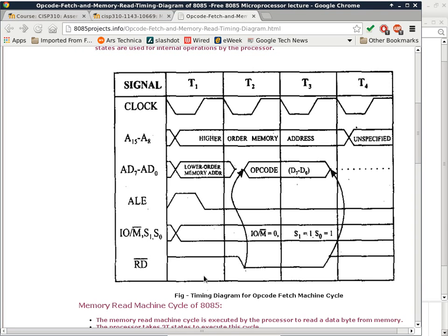So an instruction just dealing with the memory bus can easily take up 9 cycles? Because 3 to read in the instruction, 3 to read in a number to process. Let's say you only have 1 operand that you need to read from memory. And then 3 more to write it back into memory. So we're talking about 9 memory cycles to increment a number that is in memory. And that's not even counting the amount of time the ALU requires to do the actual processing, which is at least 1 clock. So we are talking about 10 clocks just to do one single instruction.